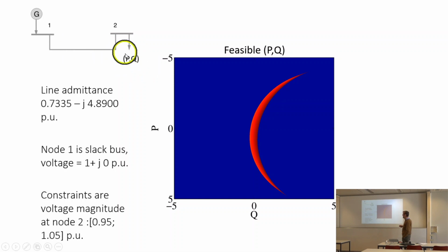So this is the only control variable. But we have these constraints here. Those constraints, I can compute them by doing a load flow. Right? The load flow will tell me, if I inject P and Q in this simple grid that has only a single PV node and a PQ node, what is the electrical state that will give me the voltage here and the power there, doing the load flow, Newton-Raphson, for example.